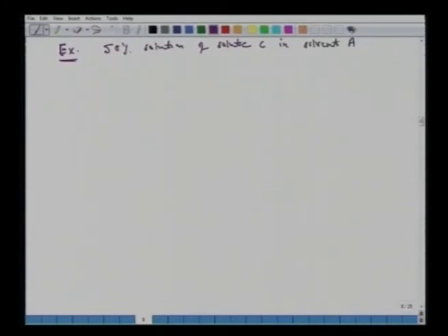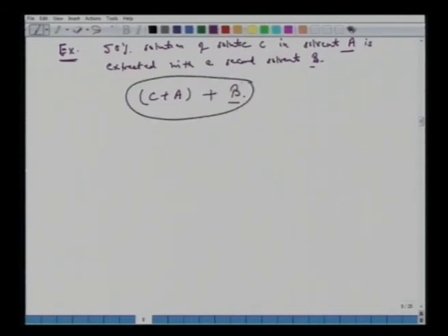So it is a ternary system. We have A plus B plus C. C is the solute, A is our feed that becomes the raffinate phase, and this B is the solvent that gives us the extract. Alright, it's given that the weight of B is 25% that of the feed. So B by F or A is given here as 0.25.